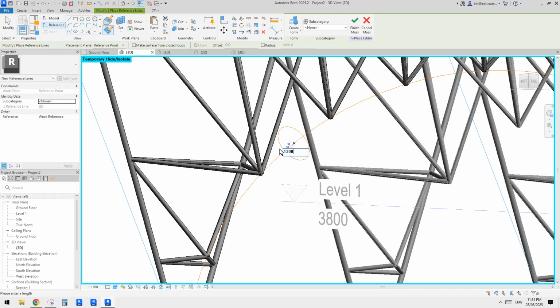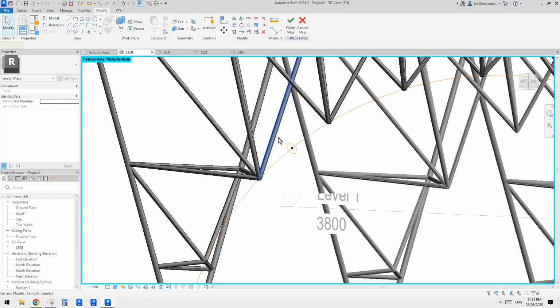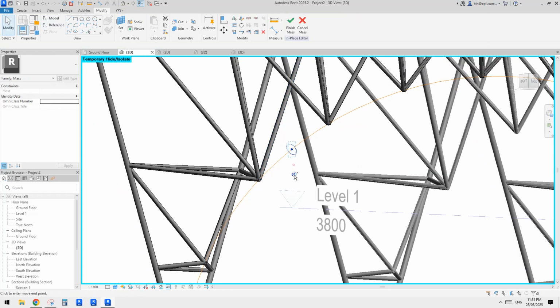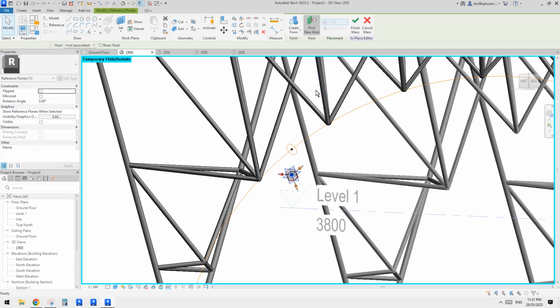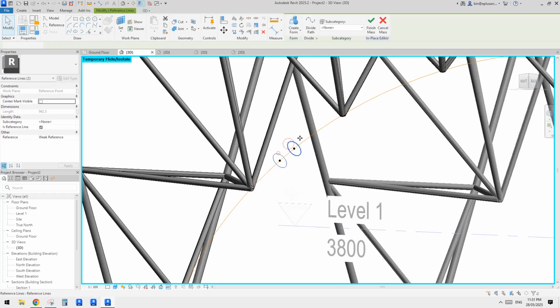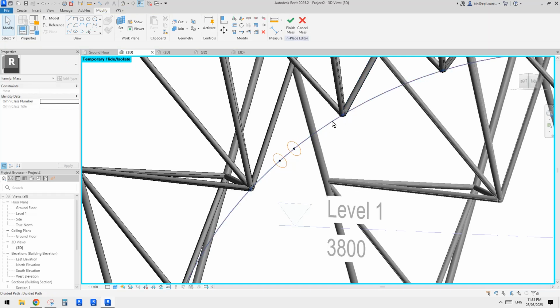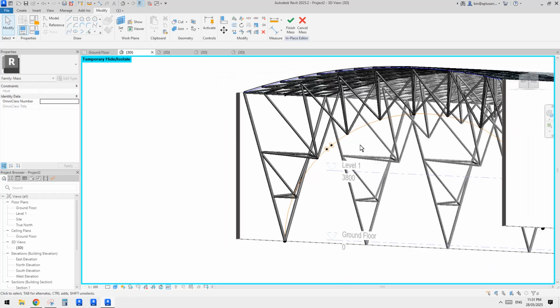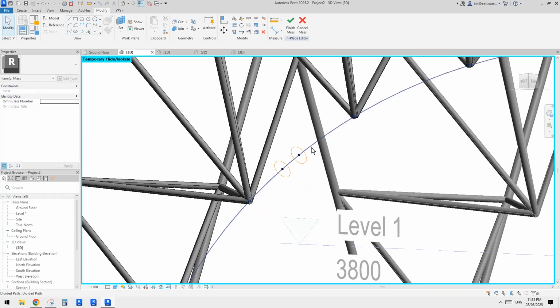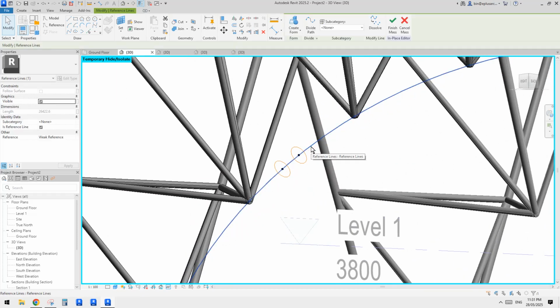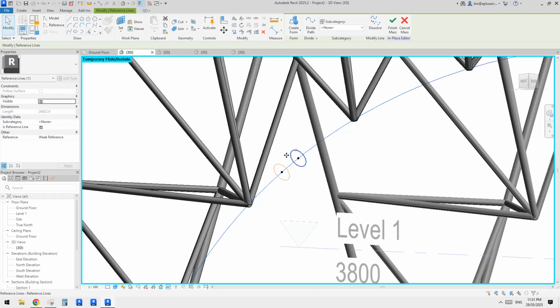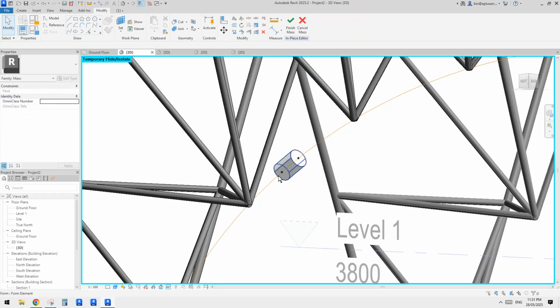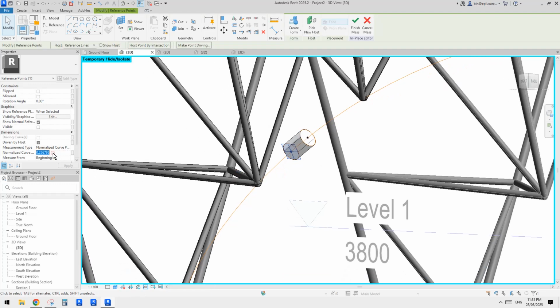So 300. So 300 diameter. So 150 radius. Okay. So I select this, copy, pick the point, pick new host, place it, select this, and this, and hang on. That's a divided surface. No, tab select. See, reference line. Control select these two, create a form. That's it. So place this to 0, place this one to 1.